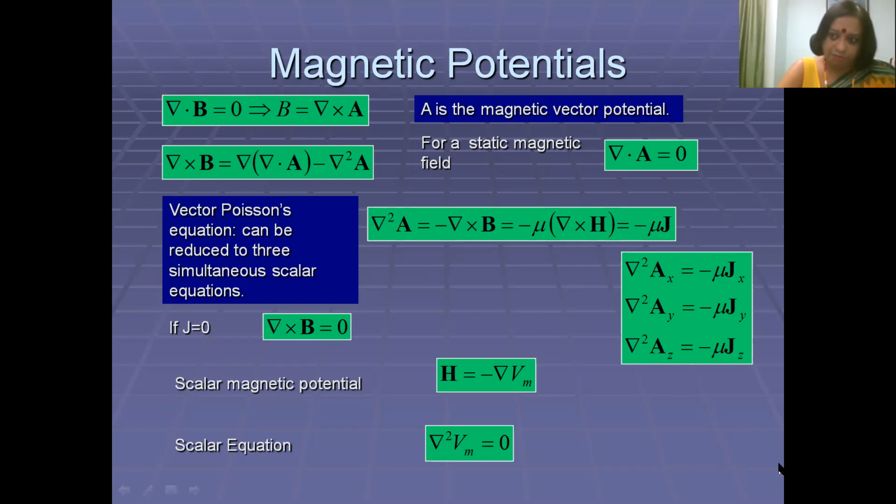Darshan, is he here? Yes, ma'am. Tell me. You understood my question, right? Yes, ma'am. Ma'am, in the electrostatic program, we have one component. So can you not call the program 3 times with Jx, Jy, Jz and independently solve for Ax, Ay, Az? Yes, ma'am, probably. Yes, there is no probability about it. You can.